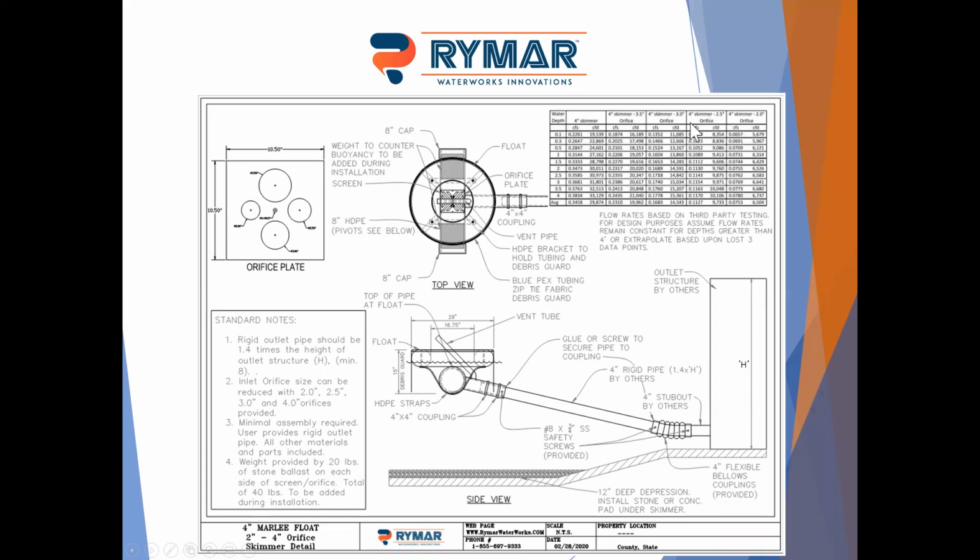Again, all of our skimmers have our flow rate for each orifice configuration, and all those again are third-party tested to verify. All of our skimmers come with this flexible coupling. If you're familiar with a Fernco style coupling, except we have bellows in it to make it flexible. So this will bend at least 90 degrees, probably closer to 135 degrees. Very simple to install. It's just a couple of pipe clamps. We do recommend you put some screws in it just to help hold on. In summer, slick PVC against slick rubber could pull out. We haven't really seen that happen, but we just provide that as a safety mechanism.